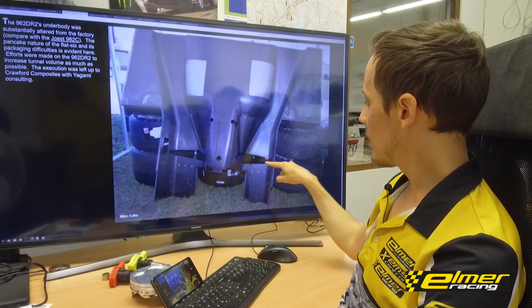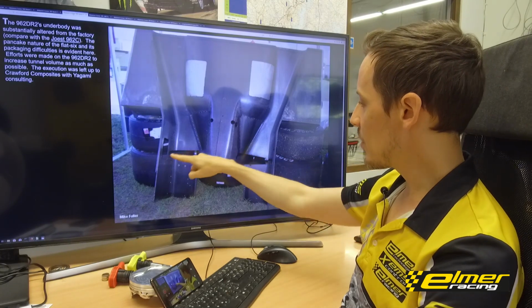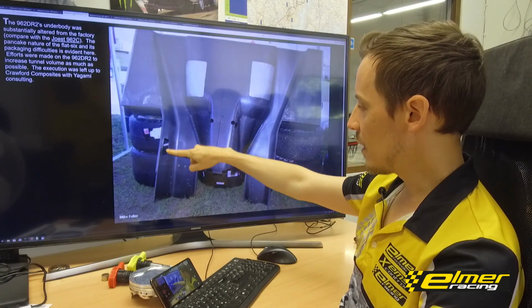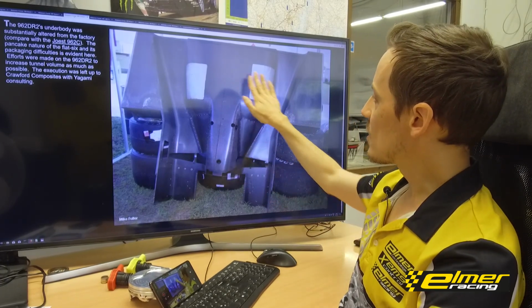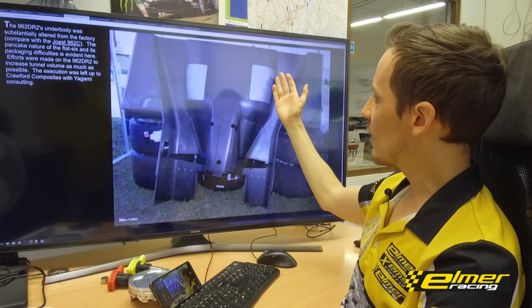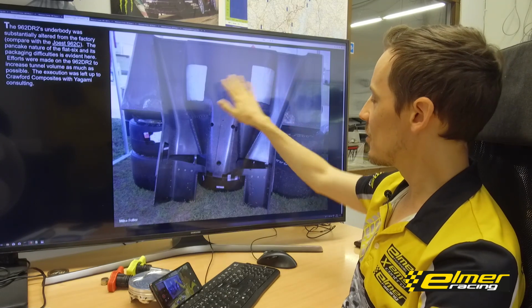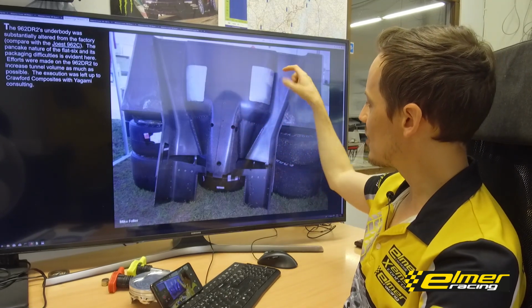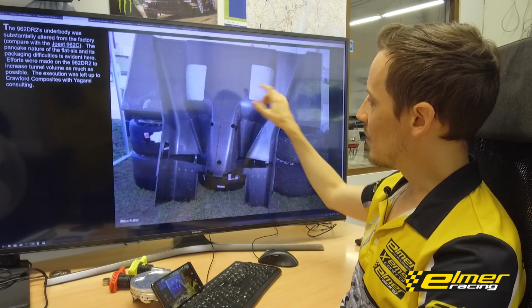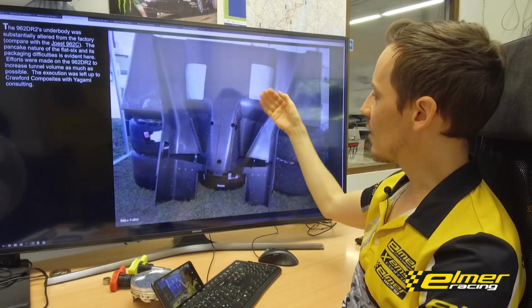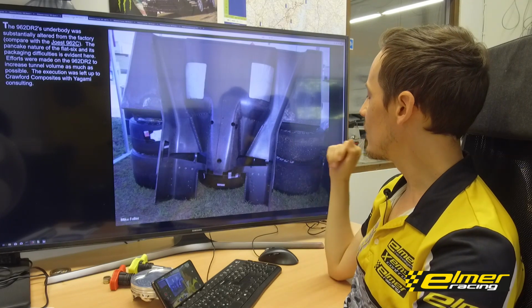And yeah, we have cutouts here for the half shafts apparently, and these second cutouts are probably for the lower A-arms, I would assume. And yeah, you have this large flat section here where you don't have the possibility of using these tunnel shapes and getting optimum area ratios, because the engine is basically blocking a lot of that tunneling, so you're losing a lot of potential here.